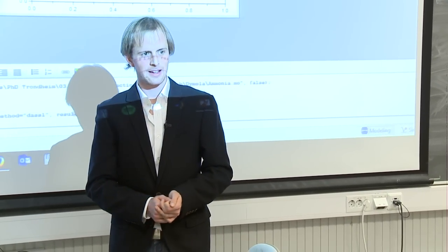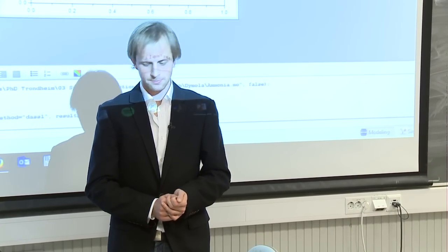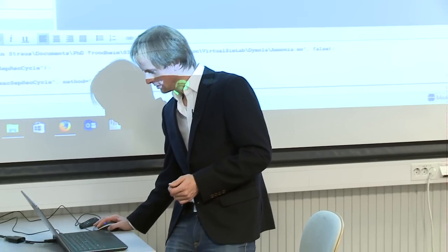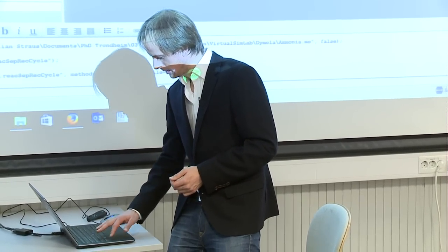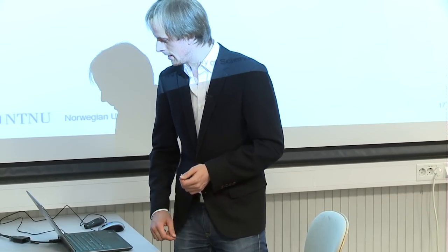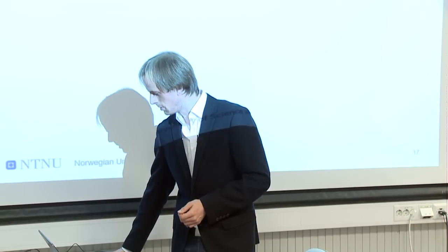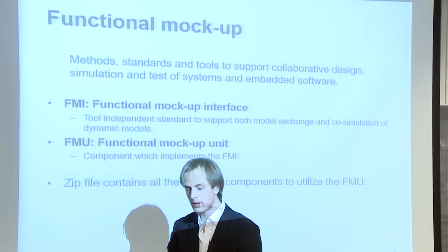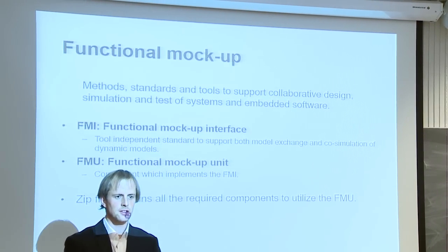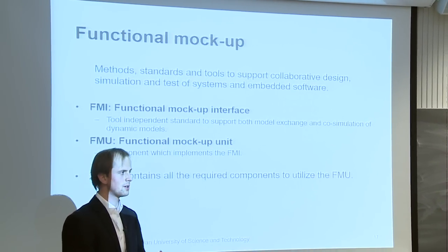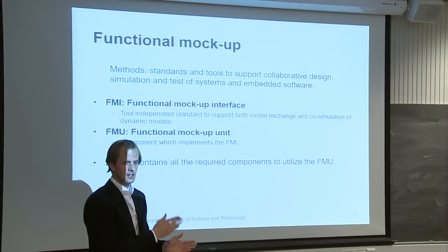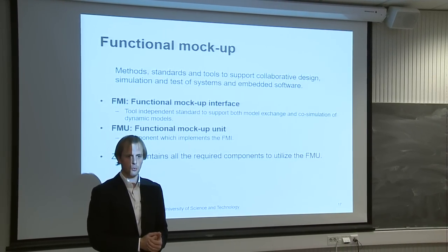However, you can export from Modelica to different software, and that is with a so-called functional mock-up. With the functional mock-up interface, you get a code which you can export, for example, from Dymola to another software.